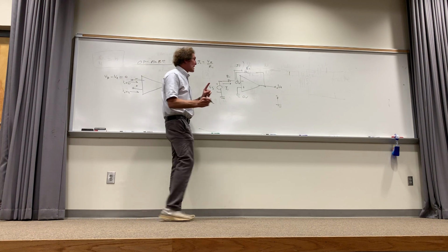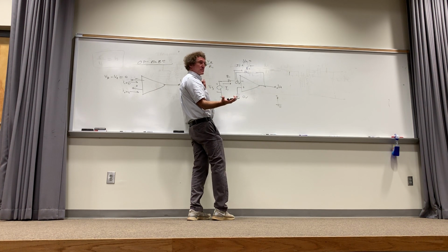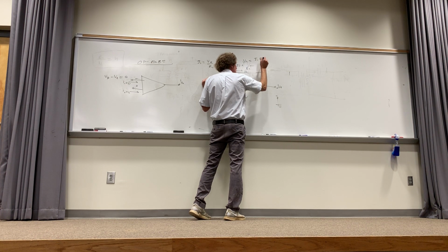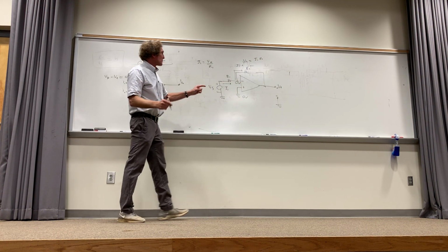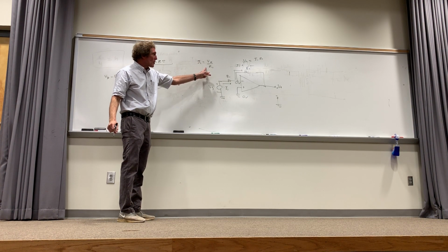Now, with that in mind, what is the voltage plus to minus here, V2? I1 times R2, right? Y'all agree with that? Not done yet. Well, what's I1? Vs over R1.